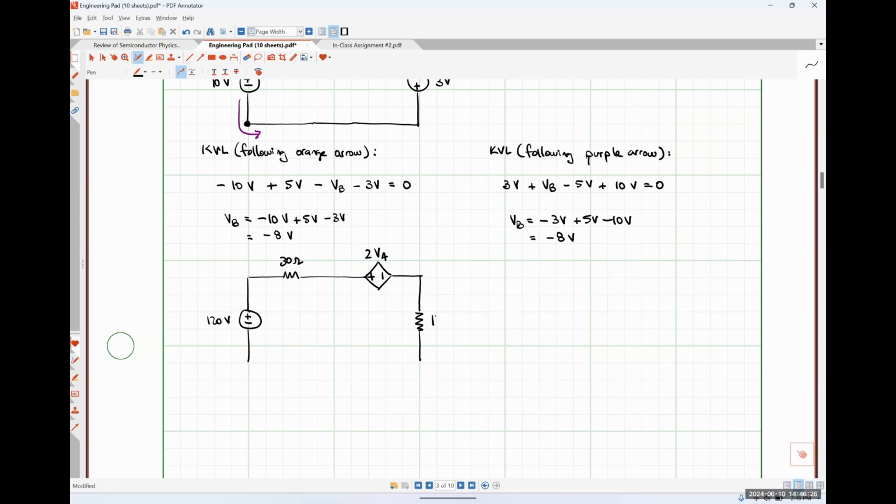Here is a 15 ohm resistor. And let's define the voltage VA to be the voltage drop across the 15 ohm resistor, defined with the positive polarity on bottom. Okay. So here we're going to wind up applying Kirchhoff's voltage law as well as Ohm's law, with our ultimate goal being figuring out